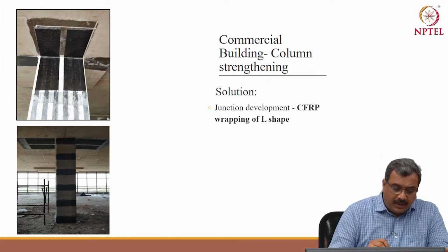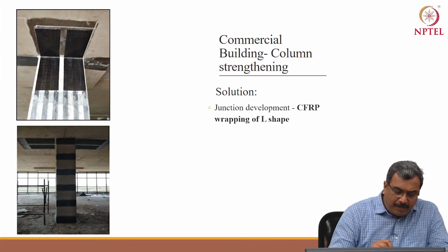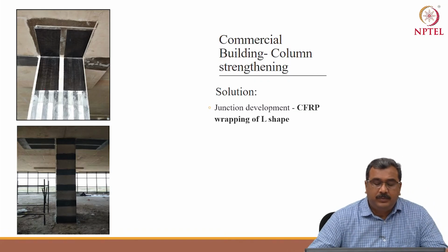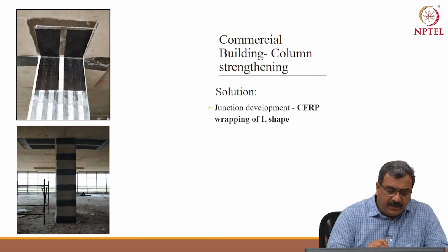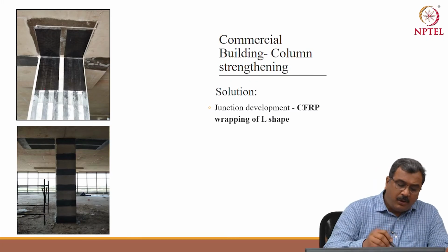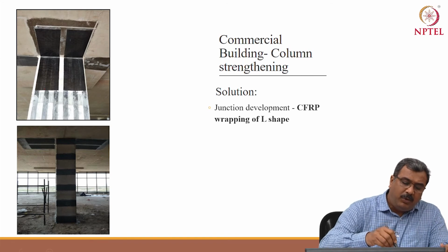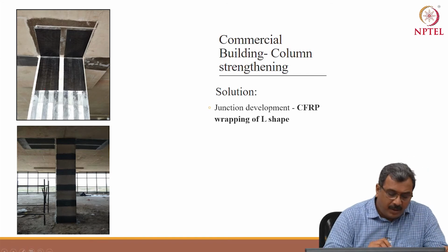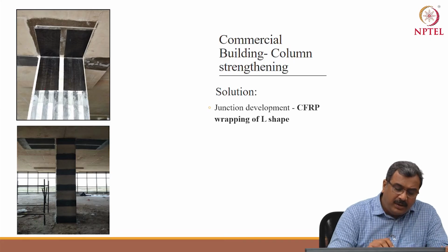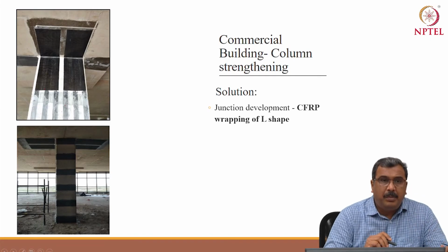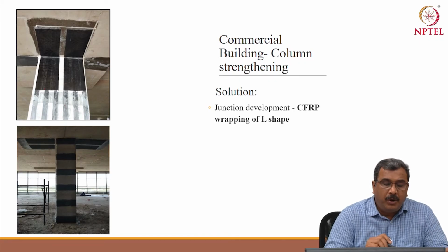Further, this type of CFRP wrap band has to be installed all around the columns. This will help in enhancing the shear capacity because of the enhanced moment carrying capacity due to laminates also, and it will not allow the laminates to bulge out or debond.